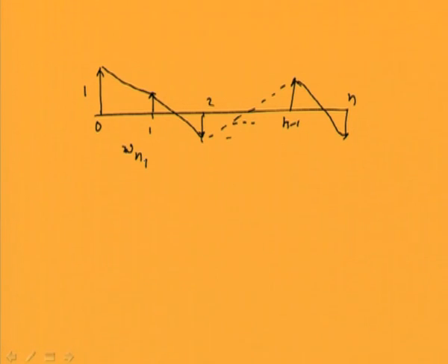Now similar mode shapes we can obtain for other natural frequencies 2 or 3. What we have to do is carry out the same transfer matrix equations to relate various displacements corresponding to these natural frequencies. So in a particular multi-degree of freedom system, if we have n natural frequencies, obviously we will have the corresponding n mode shapes.